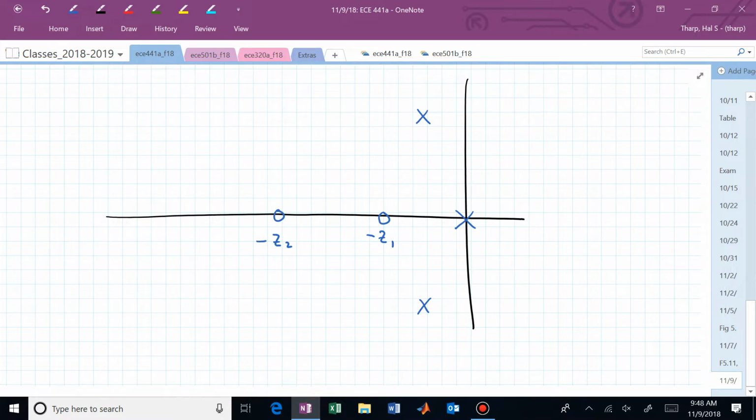We've cut our bread into more pieces, haven't we? We've now introduced 2 more cuts on the real axis. We have 1 piece of our root locus there. We have another piece there. This pole at the origin is going to go towards minus z sub 1. And what happens to the poles? Again, we have changed the pole zero excess with this PID controller. That's why it's so powerful in this class. We've now eliminated one of those poles effectively.